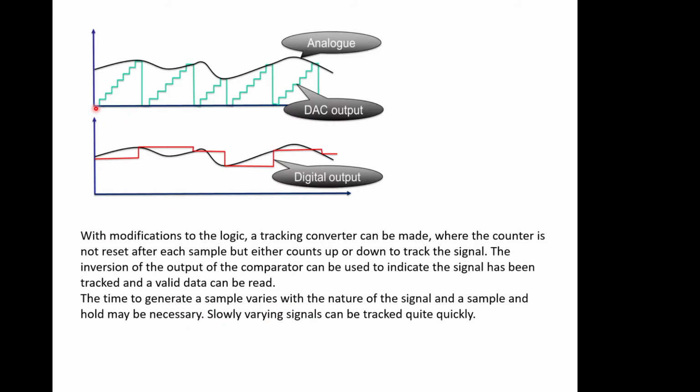Easily what's seen in this kind of arrangement here. So we've got a signal coming in that we're interested in. We start the conversion, we start clocking up the counter, and when it reaches the level, we stop the clock and read the reading out. Obviously, this works quite nicely, but high voltages take longer to digitize than low voltages. You can see here the time to conversion, if you like, is a short time, whereas here it's a long time. So it's non-deterministic in many ways,